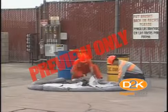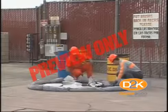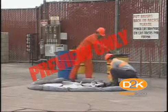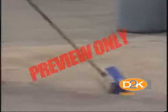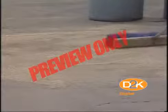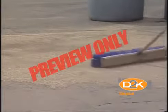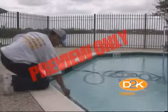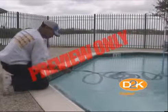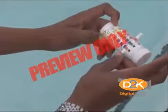5. Dispose of wastes and spills safely. Immediately clean up and properly dispose of any chemical spills. If the spilled chemical is a solid, carefully sweep it up using a clean broom and shovel and place it in a clean, dry plastic container. Avoid breathing the dust. If possible, dilute the chemical in water and add it to the pool or spa. Then test and balance the water.